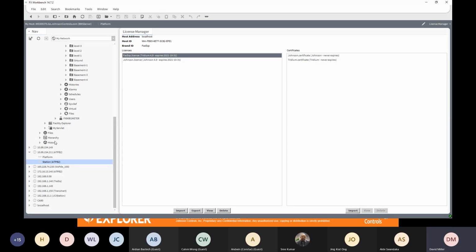So when it came to displaying that Distech device, my Workbench won't have the necessary software, the necessary module, to display that item. What we might get is the tree come up, and we might be able to navigate around, but when we get to the node that's important and we try and display it, we'll get an error that says can't display or module not found. So we might be able to do 80, 90% of what you need to do. But depending on what it is, we might not even get the first initial load of the tree.